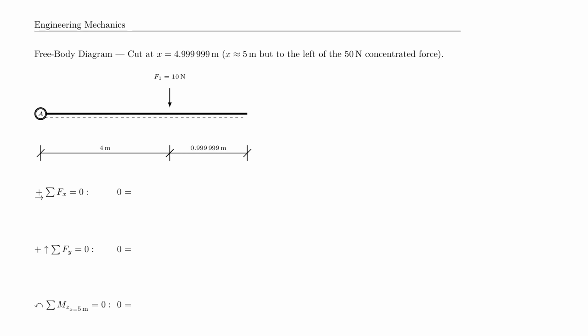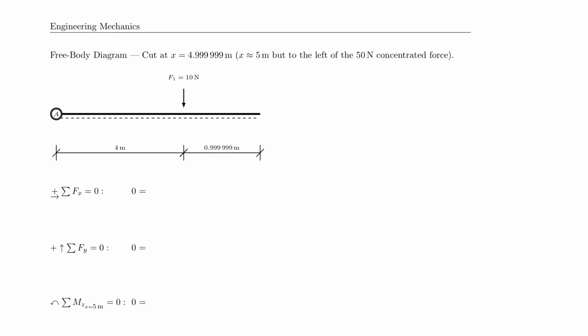And as always, we have to bring in our external forces first. So let me start here with RAY, which I believe was 11.3, and my horizontal support reaction was equal to 43.3, pointing to the right. Now I want to bring in my cut. I'm cutting right here, and I therefore have to now bring in my external forces, which are technically internal forces, but I bring in my shear force, I bring in my normal force, and I bring in my moment.